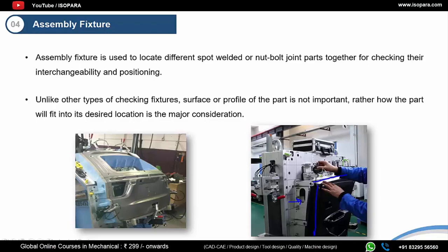And then here you can see it is the same measuring device which checks the tolerance. It will be inserted at these specified points here, and it will display the value on this small screen. So with this we can check whether these edges are under the required tolerance or not, and this is just to check if the door panel will fit in its desired location.